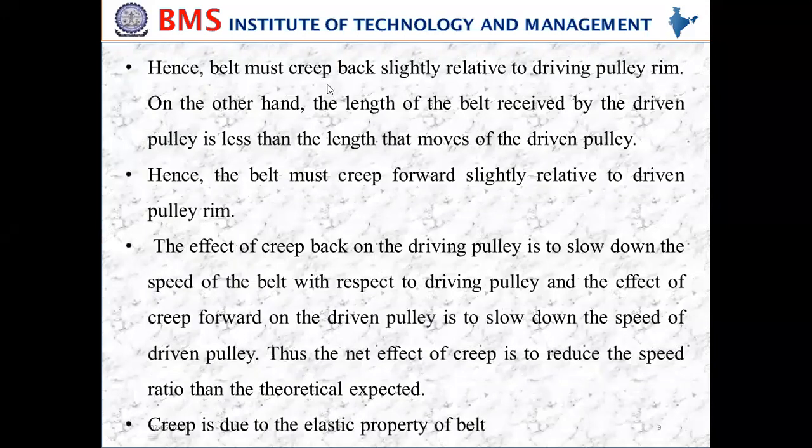Hence the belt must creep back slightly relative to the driving pulley. On the other hand, the length of the belt received by the driven pulley is less than the length that leaves the driven pulley, so there is a creep forward slightly. Hence the belt must creep forward slightly relative to the driven pulley.